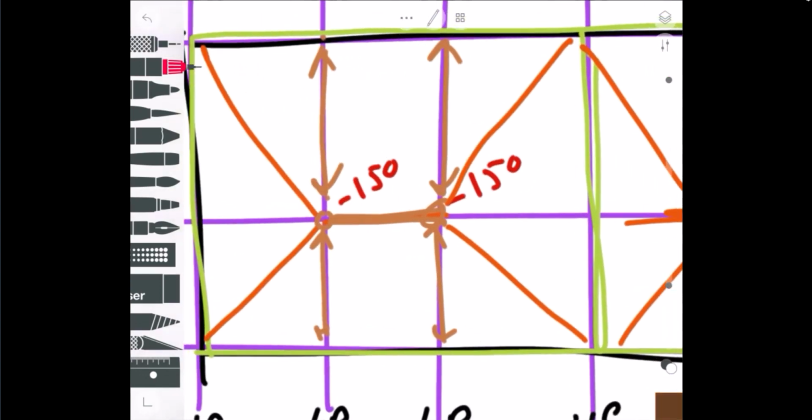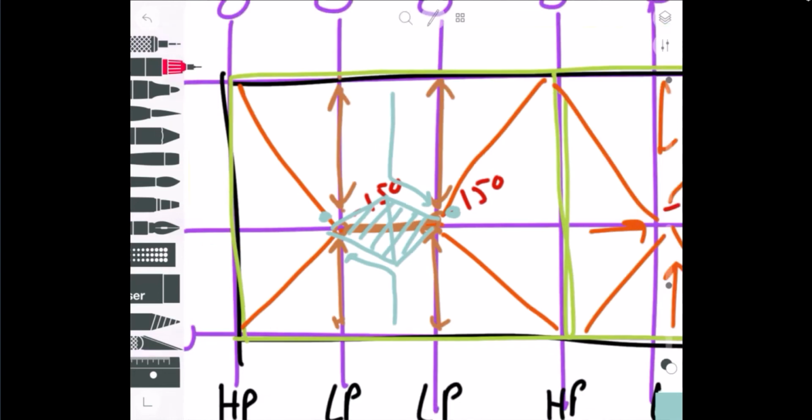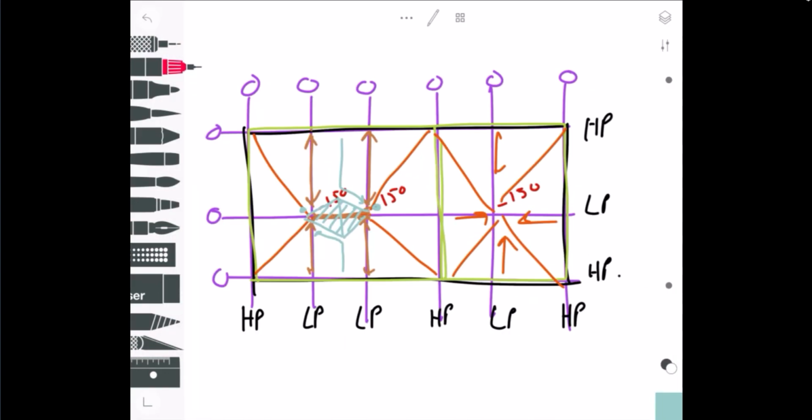So that's an example of where we would say, okay, let's do a little bit of sloped insulation. At this point you could just taper some insulation in a little cricket like this, so that when water comes down, it gets forced over to a drain that would presumably be sitting somewhere around here. Water comes down, it forces down this cricket. So you have a small area of sloped insulation right there. And that's how you deal with that. That's kind of the second foundational thing you do when approaching these roofs.